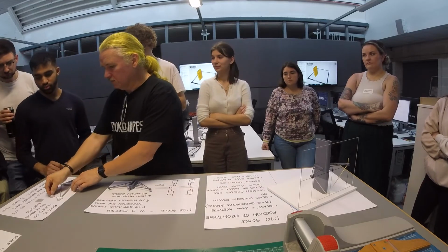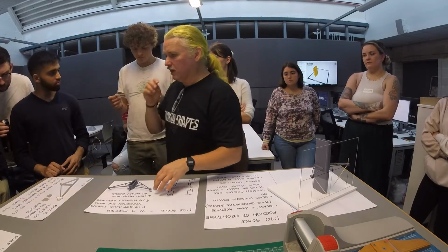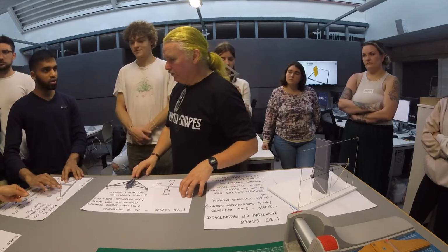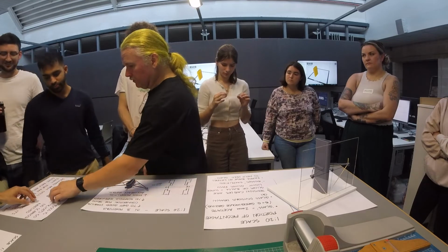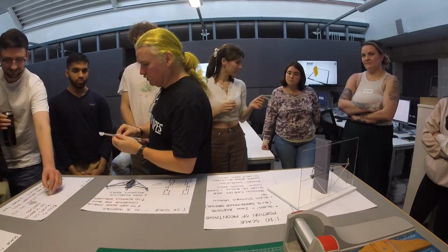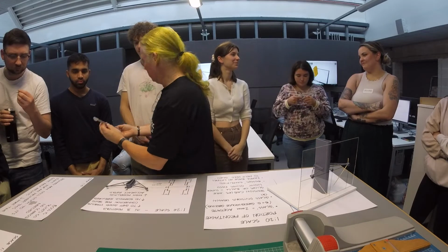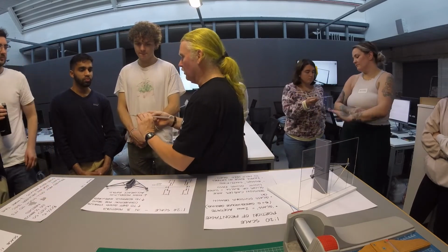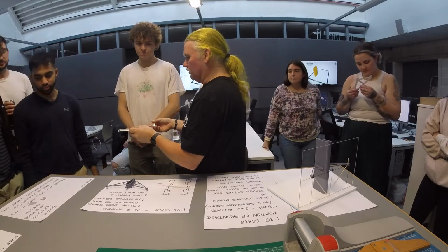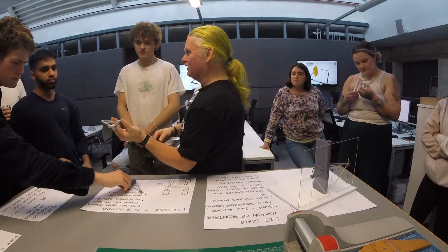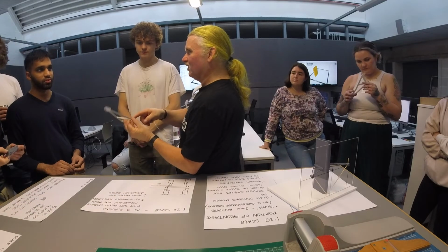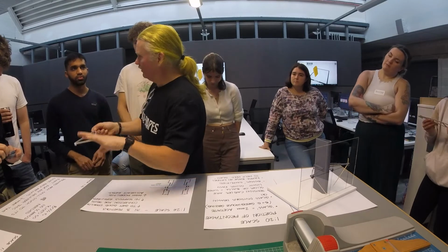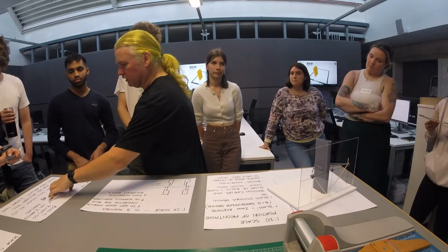We're not aiming for perfection. We're trying to get a model done in the right amount of time. This can be sanded as well, yeah? Yeah, yeah. And you do end up with a few tool marks. You know, you can definitely tell the underside. They're pretty ugly underneath, so you kind of be aware of that. I wouldn't just make 2 of these and have one of them upside down, because that one's yucky compared to that one. See what I mean? I would actually print one that is the other way around, mirror it properly.